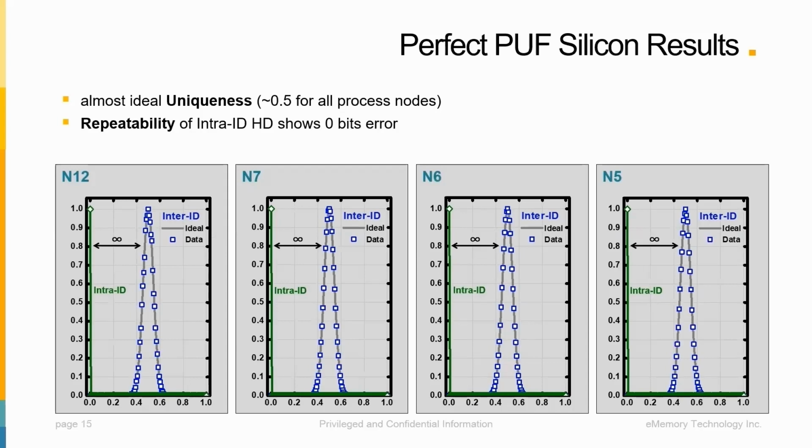Unlike humans, we may have a different response to a single trait. In the digital world, the ID is a string of zeros and ones. If today an ID is composed of 5 bits, and I tell you the other ID is 100% different from it, you would immediately get the other ID by simply flipping the zeros and ones. But if I tell you that the other ID is only 50% different from the known ID, we will then have to calculate all of the possibilities and perform trial and error to get the correct ID. This is why 50% is the best uniqueness trait for a digital PUF.